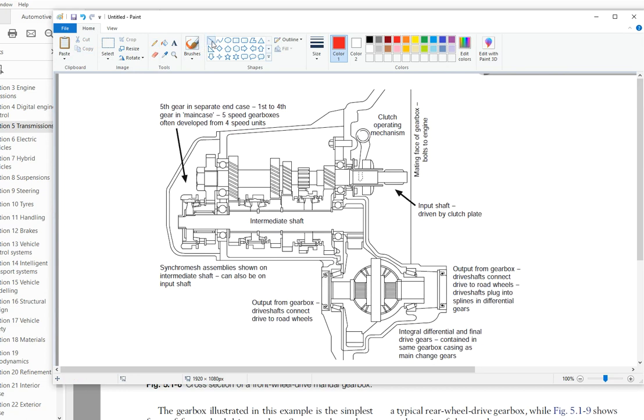No, it's this one, and it's red, and it's the thickest. I'm looking also at the size of the gear. So this is the smallest of the pinions. They grow in size as we get into a higher gear. So the actual first gear is going to go this way and via the synchronizer to the final drive and to the wheels.